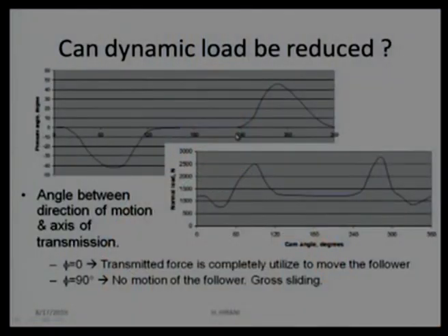We can't say that pressure angle 0 is possible. It is possible, but because of some other constraints we will not always go for pressure angle 0. Maybe for a few degrees, some chunk, yes, that is also shown here from 120 degree to 240 degree. Pressure angle is almost 0 and the force is steady. In other words, this much force is sufficient to serve our purpose.